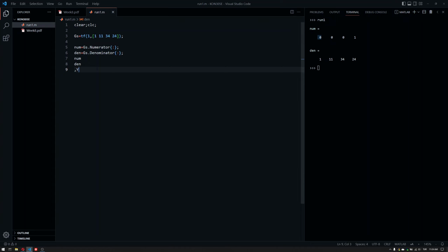So y is equal to Cx plus Du here. And if it's not biproper, if it's a proper transfer function, D is always going to be 0, because this is the direct connection between input and output, and you have to be able to partially fraction this transfer function if you are going to end up with D. If it's a proper one, you don't really need to bother with that because D is 0.